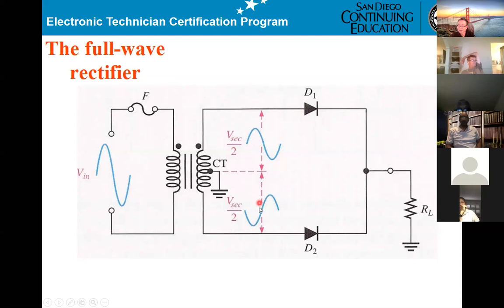That means you get this part of positive coming out. When you get the negative part here, then it will be positive on this side all the time. They have to be opposite. If negative here, then you get positive, and this positive turns on this diode, and this positive comes out again. So that's why you get full wave. This picture will show you more clearly what's going on at the secondary for the center tap transformer.